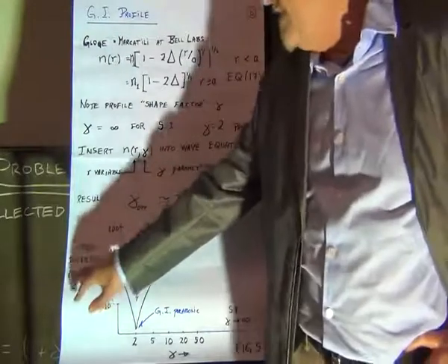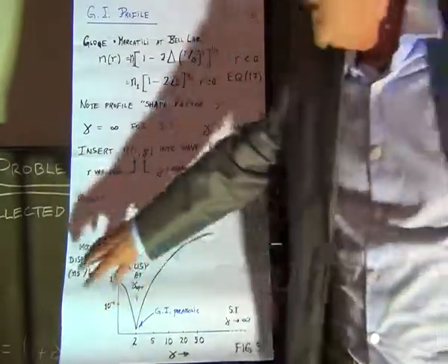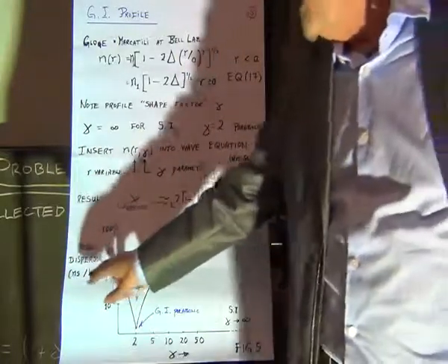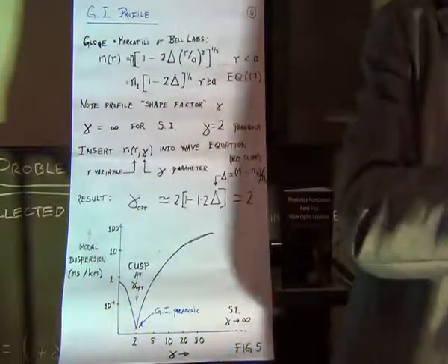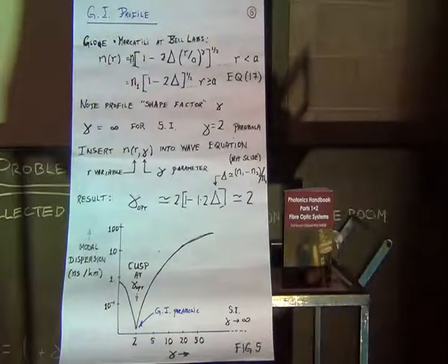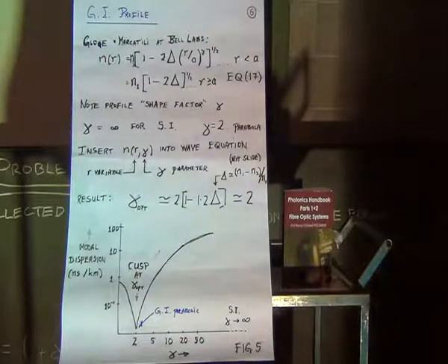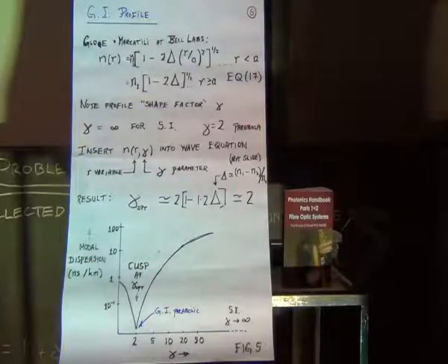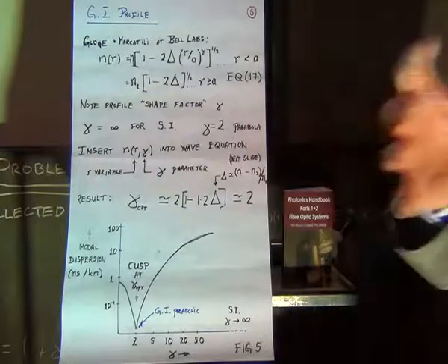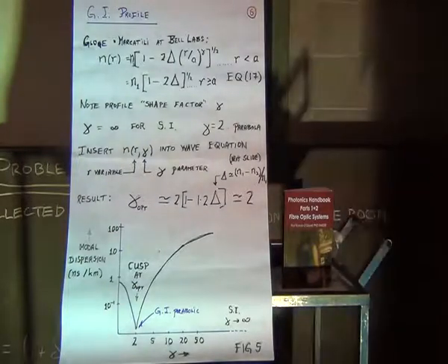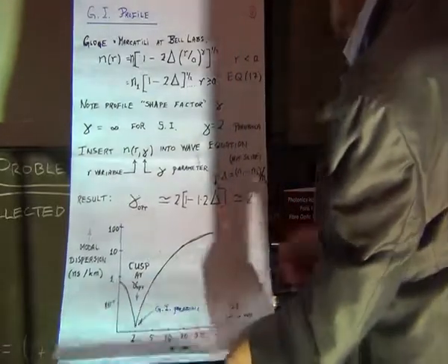Notice that if you take the amount of nanoseconds spreading per kilometre and turn it upside down, nanosecond becomes gigabit and per kilometre becomes times kilometre. So the inverse of that quantity is the bandwidth distance product. It tells you how many gigabits per second you can use and for how long a span before you have to repeat the whole thing all over again. Go into a detector, square it all up again, equalize the whole thing and put it back out through another laser. So we keep that in mind, that inversion